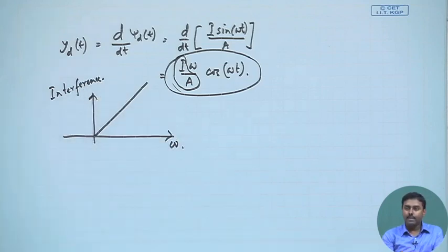Here, remember, deliberately we have taken out the signal. So we should expect after FM demodulation 0, nothing, but we are getting something and we are calling that interference. That was just to make the overall analysis simplified. If you give FM, then there will be more involved terms. So we just wanted to simplify that. We are just capturing the interference effect.